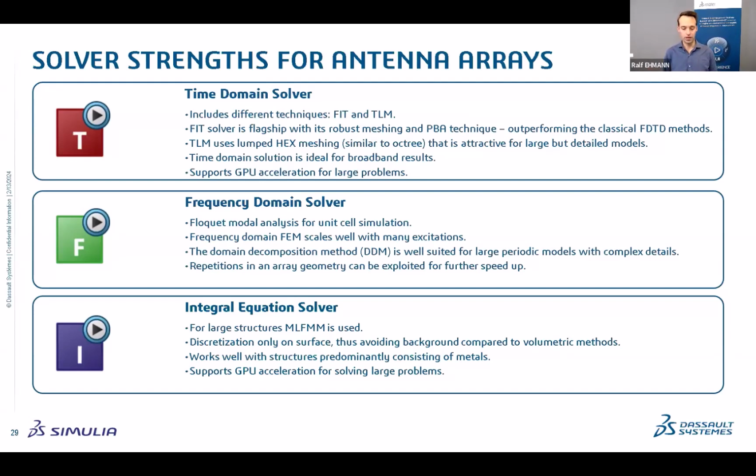Both support GPU acceleration. And then there's the frequency domain solver, which we've been using for infinite arrays for a long time with Floquet modal analysis. But we've also recently introduced the domain decomposition method, which is well suited for large array models with complex details, where we're able to exploit repeatability within an array geometry to really speed things up. And might I also say, coming to the finite element method in itself without DDM, with a direct solver, it scales very well with many excitations, although we would recommend DDM in such a case.